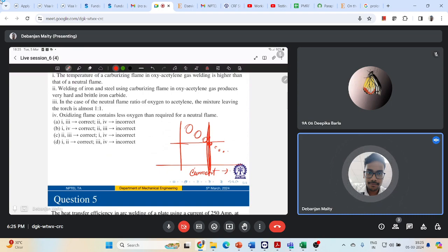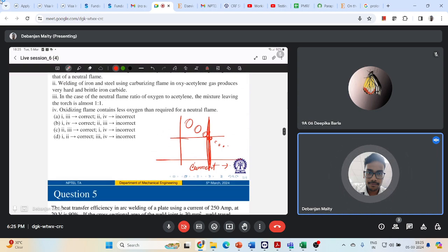So at low welding current, my droplet diameter will be more than the electrode diameter, and I will end up with globular metal transfer, right? And yeah,